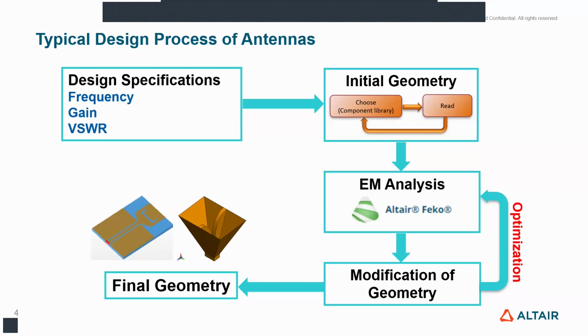Okay? And whenever you start, the initial design may not meet the specifications straight away. So it would be an iterative process to fine-tune the design, either manually or using built-in automation tools in software tools like FEKO. And after such an iterative process, you will have the final design that meets the desired specifications.